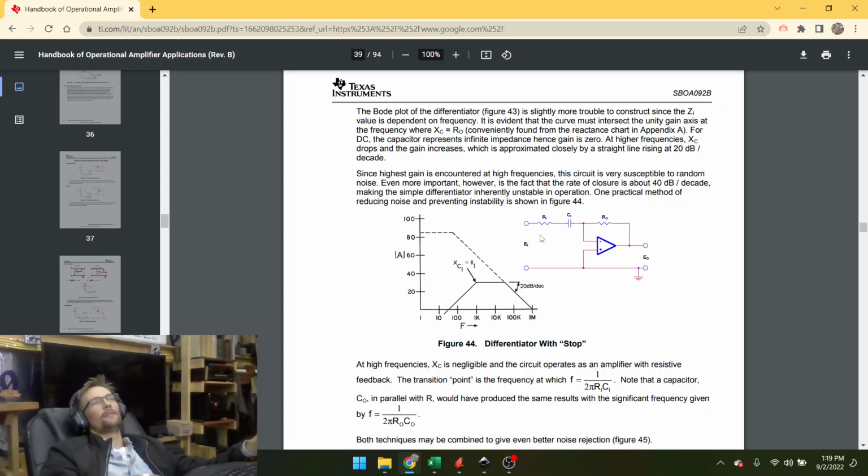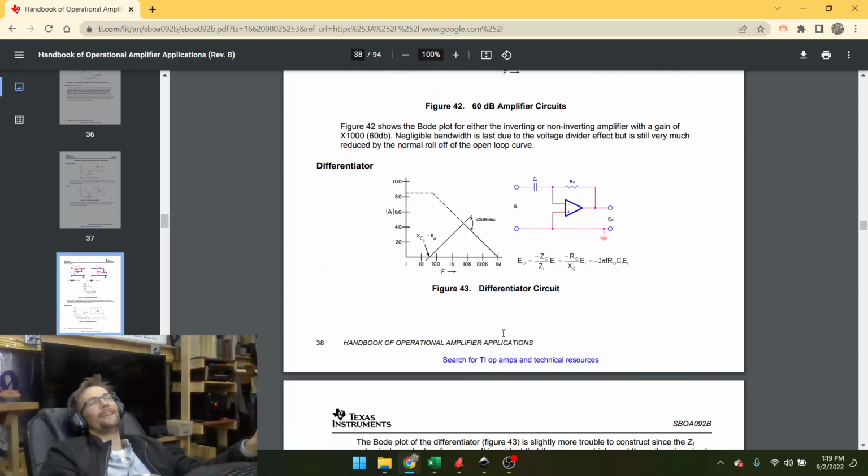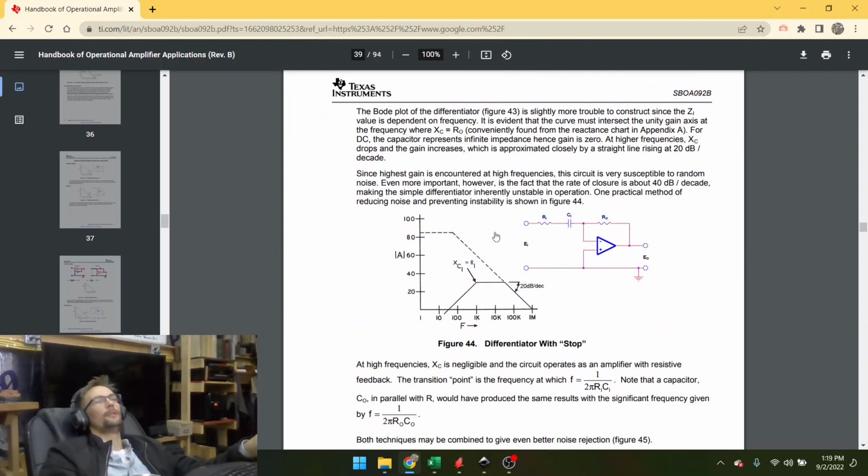And when you add this resistor here, it adds this plateau on the top. Oh, cool. So the parasitic resistance in the CI is what will cause this to dome, or kind of plateau up at the top, so it'll kind of come up and then, interesting.